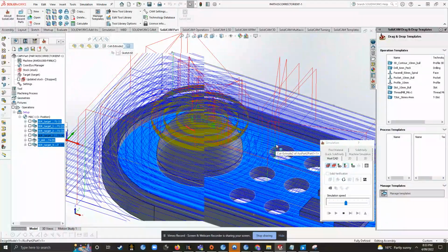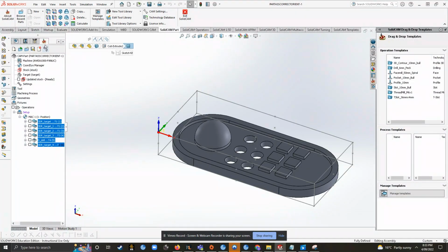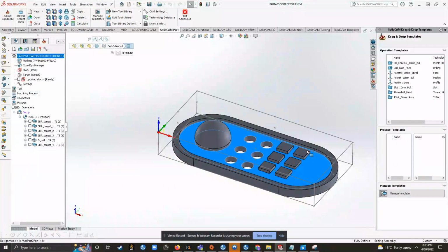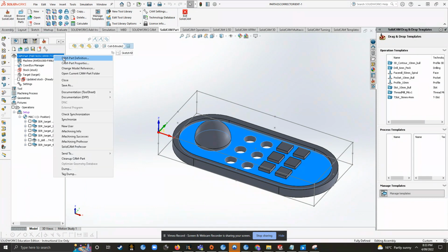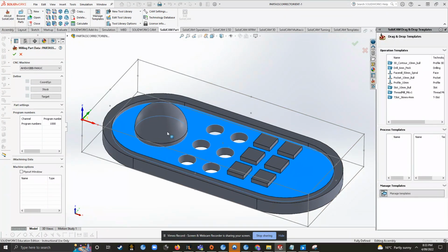Just taking a little bit to load there. So I might just go into how I set up the part. I made my geometry to my unique dimensions, and then set the stock dimensions, which is just the maximum box dimensions for this part. Establish the coordinate system in the top left there, with the y-x plane and z being the extrusion direction.